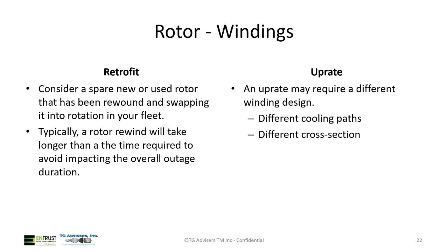I mentioned early on that you want to consider whether you have hard coils or GVPI. If you have a GVPI machine, the rewind is going to take significantly longer. In some cases, there's a higher risk for core damage.